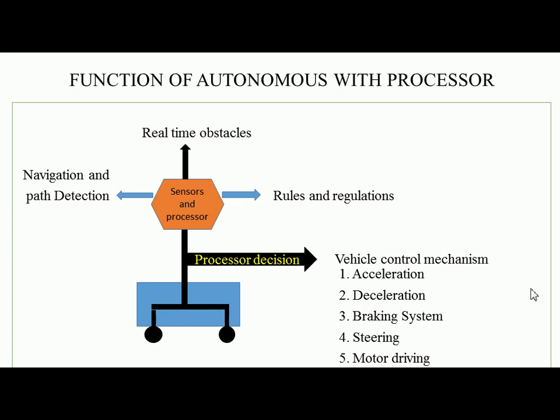So it is too tough for the robot to make a turn on a carpet, even with tape on the wheels. So I want to implement omni wheels, which consist of plastic and rubber, so that it will improve the steering compatibility.